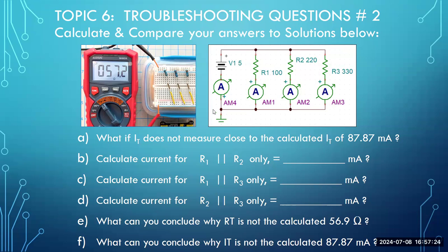And so a possible scenario is, as we've discussed before, one of these is defective, and that leaves you 2 remaining. In the previous calculation, you did calculate R1 parallel with R2, and that calculated to be a specific amount of ohms. You recorded that. And so when you're calculating the current based on those ohms, you're calculating 5 volts based on the amount of ohms for R1 parallel with R2.